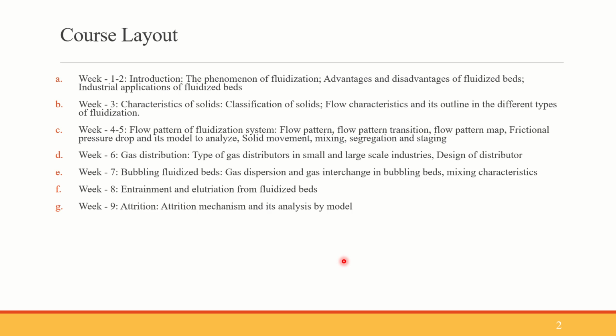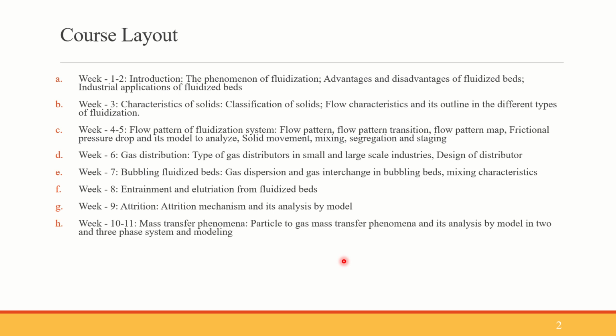And then it is about attrition mechanisms. Attrition is just the breakage of the particles by shear forces or fractional breaking; surface wear and tear can also be there, or fragmentation of particles can also be there. For that also we have seen different models. And the last is about mass transfer phenomena happening inside the bed, particle to gas mass transfer and its analysis in two phase and three phase systems and modeling, and also the heat transfer phenomena, heat transfer between fluidized beds and surfaces, and modeling.